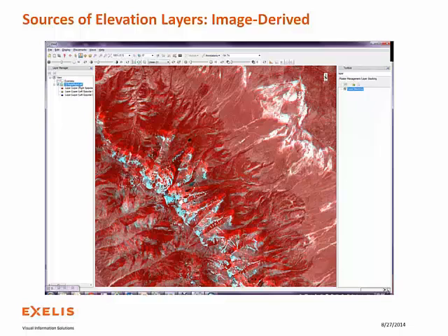So what you end up with are epipolar images where the right and left input pair are oriented in such a way that each of the ground feature points have the same y coordinate in both images. So you end up with this sort of overlap effect that you're seeing here. What that's called when it's displayed as an RGB combination is an anaglyph. And this anaglyph image, if you have the 3D glasses or the anaglyph glasses, one side's red and one side's blue, does display in 3 dimensions.